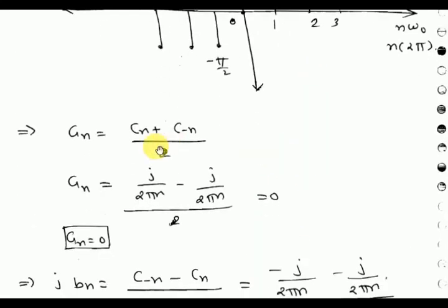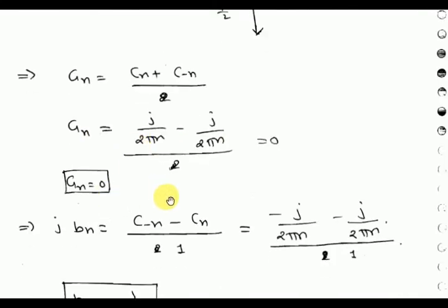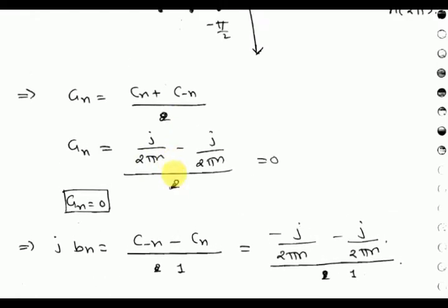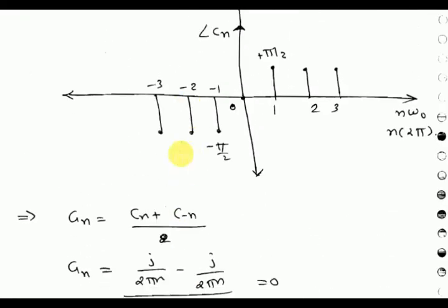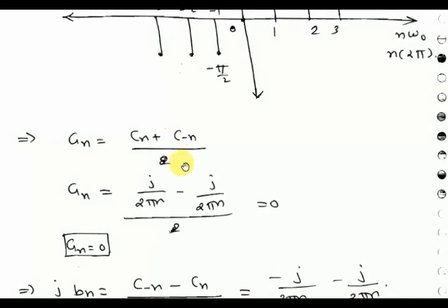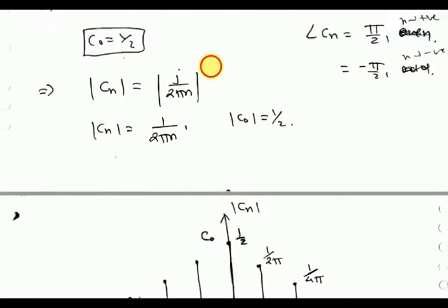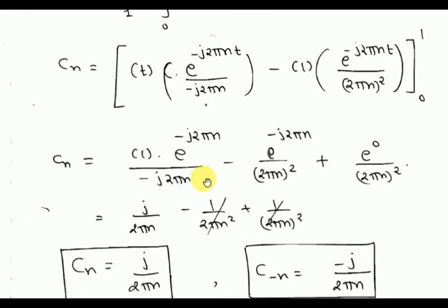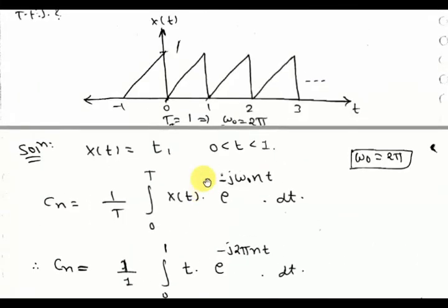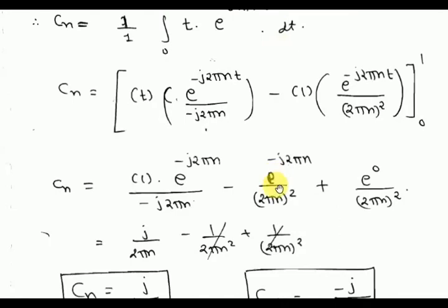Now we have to find the trigonometric Fourier series from the exponential Fourier series. We know the formula, an equals c minus n plus cn, and putting in the values, an will be 0. Why? Because this is an odd signal. Not odd, but an is 0. Let's see whether this is odd or not. This contains hidden odd symmetry. The DC value will be non-zero.